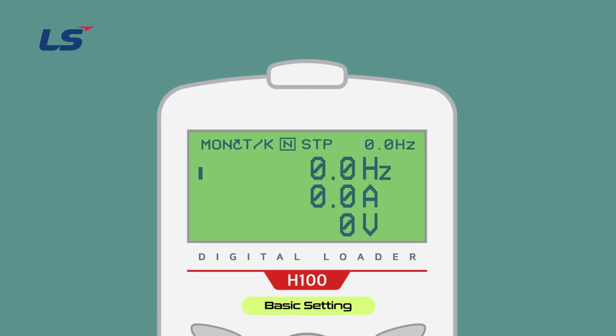The monitor components are as follows. This is a mode display. MON means the monitoring mode. As a driving direction indication, it is currently set to rotate clockwise. TK represents the command source, frequency reference source, respectively. Currently, the command source is set to terminal, and the frequency reference source is set to keypad.